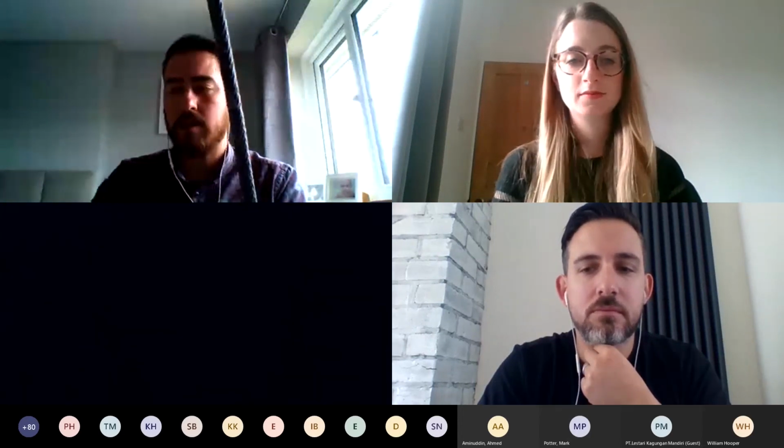And again, I'm not trying to say that to shy away from these particular cable glands or the 501453 RAC, absolutely not. But it has to be determined whether it's fit for purpose by the cable type, which is obviously the moving target, if you like. That's the thing that's ever changing, is cable specifications.